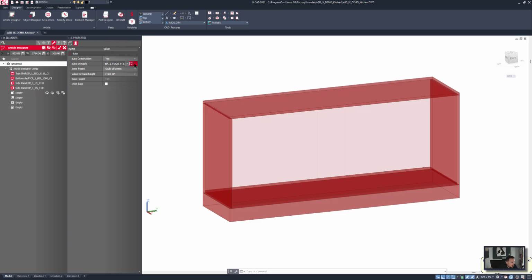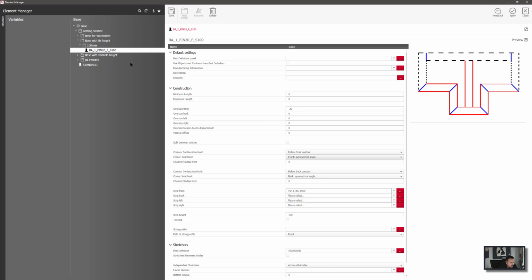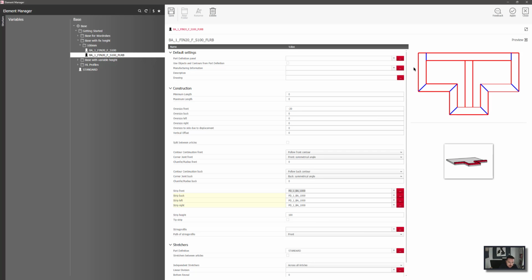And then what I want to do is have a plinth style base that's running all the way around. So I'll take this product and I'll say that this is the front, left, right and back. And then in here, I can copy that part into all of those sections and change my trims so it's mitered. I'll then say that it should be -50 on all sides.